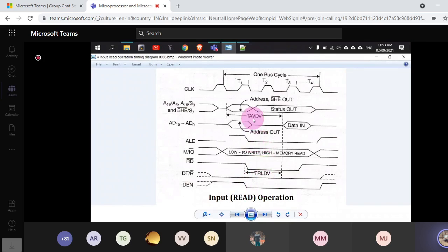If you see the data bus, it is actually tri-stated. It does not have either data or address, and that stage is called tri-stated. So this data bus has nothing to do in this stage because the actual data transfer will appear in the T3 state. In the first T1 state, you deal with addresses. In the second T state, you deal with activation of the read and write signals, and the transceiver IC will be activated. In the third T state, you will be actually transferring the data.